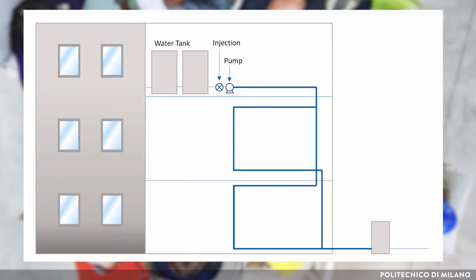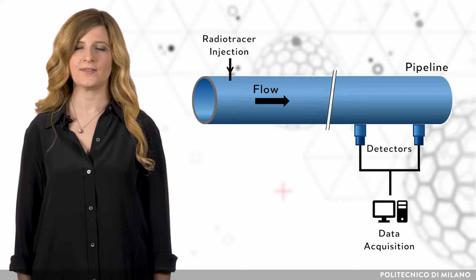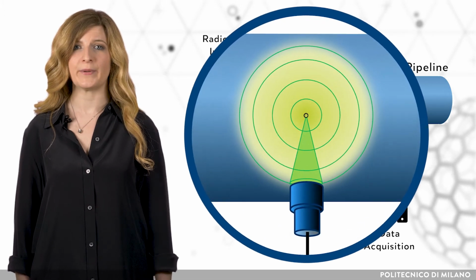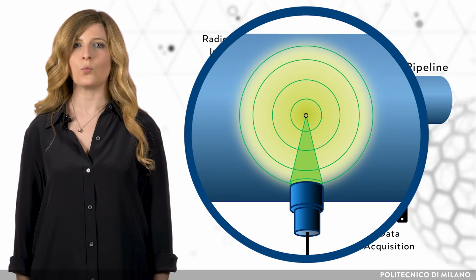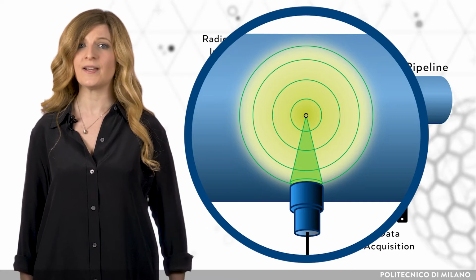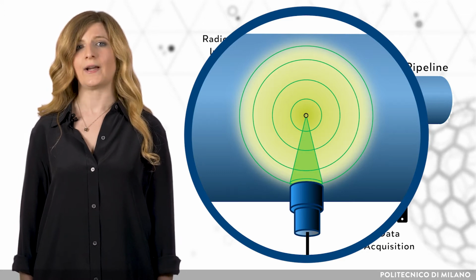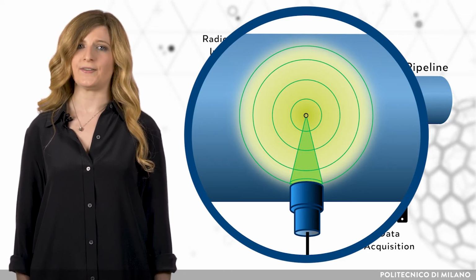The unit is divided into different sections of interest, and the detectors are positioned to completely cover the motion of the traced material. The detectors describe the inlet and outlet signal of the different sections. But ionizing radiation is emitted in all directions, so what do the detectors collect? It detects a certain amount of information within a solid angle. The amount of material inside that angle, inside the so-called detection volume, is not the same for each point. It depends on where the detector is positioned. This information will be taken into account during the interpretation of the acquired data.